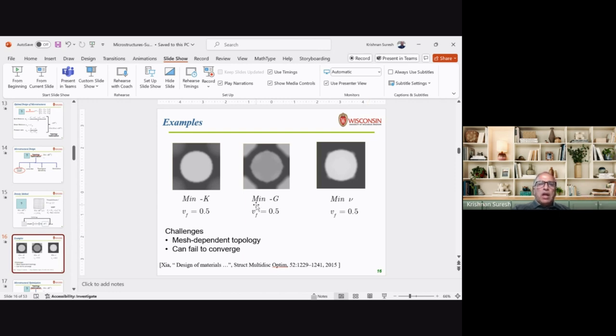For example, I want to design a particular microstructure that is stiff in all directions. You design something like this. It'll automatically design this microstructure and say, that is my best design. So these are tools that are available today. Many industries use these tools. As a different example, this is a microstructure that you'll come up with if you want a different goal. So different microstructures will achieve different goals. And that's the idea of automatic topology optimization.